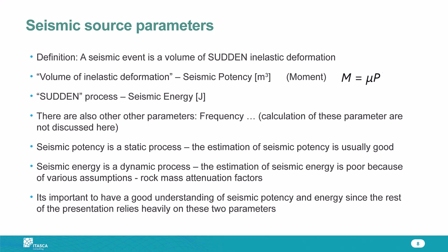When you look at a seismic source parameter, the seismic potency parameter, it basically defines the volume of inelastic deformation, and its unit is cubic meters. And I will be mentioning seismic potency many times over the following days, because I personally believe that that's the more accurate seismic source parameter that we can extract from a numerical model.